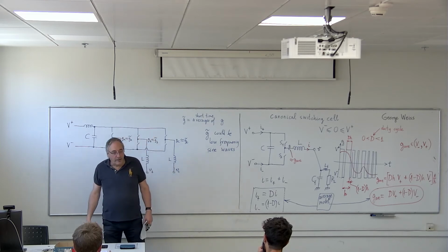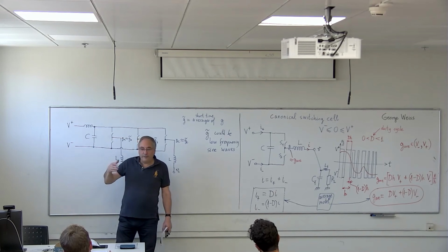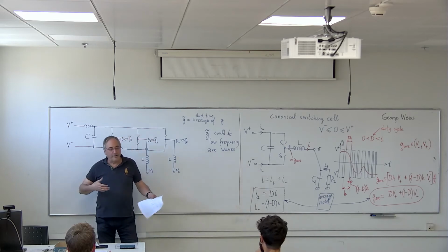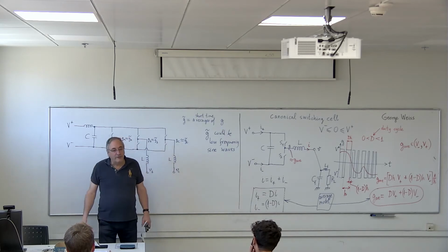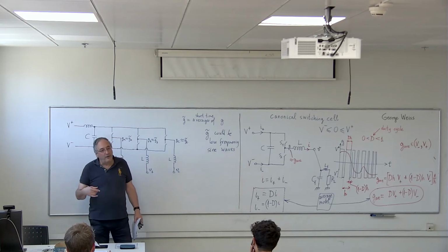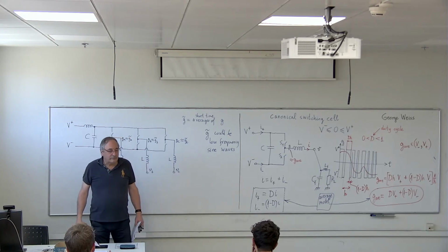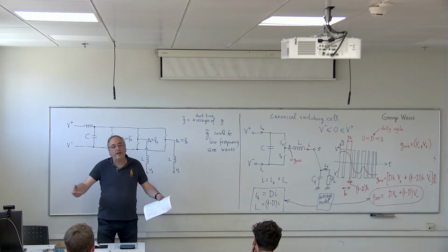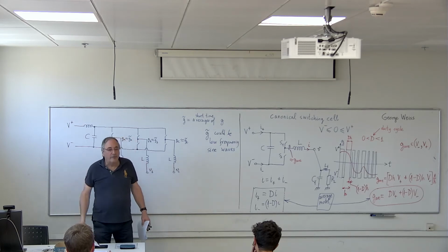But if you want to create a canonical switching cell which produces a signal for a very powerful loudspeaker, and then the output frequency range is up to, I don't know, 15 kilohertz, then you need the switching frequency to be much higher. And is there like an order, like if I want 50, then you said 10 kilohertz is okay. So in general, the switching frequency should be at least 10 times higher than the highest frequency that you want to be able to control.